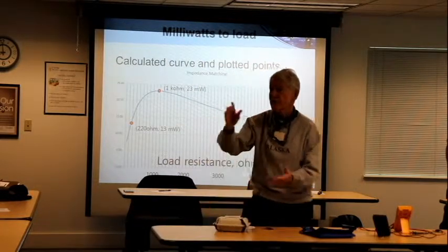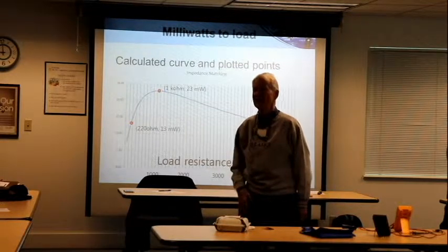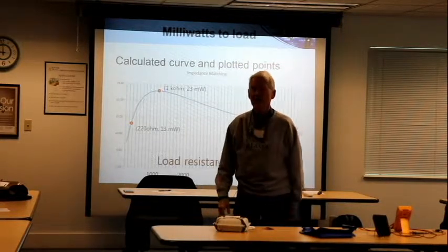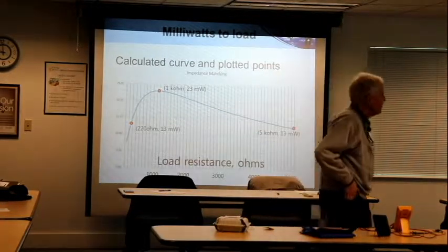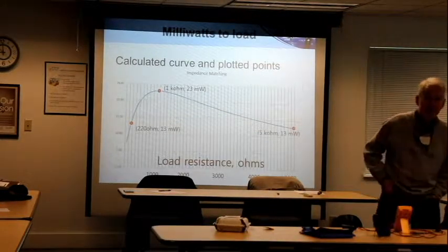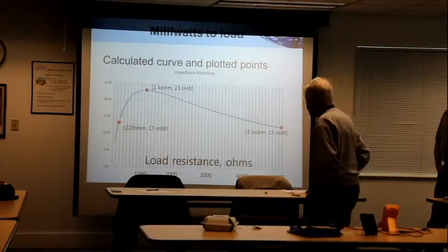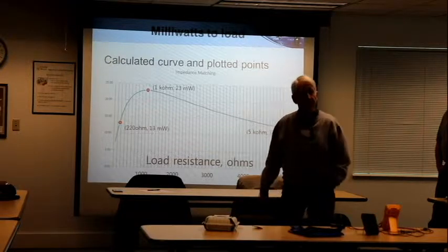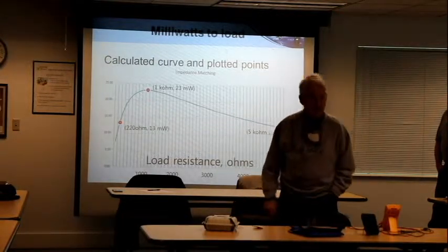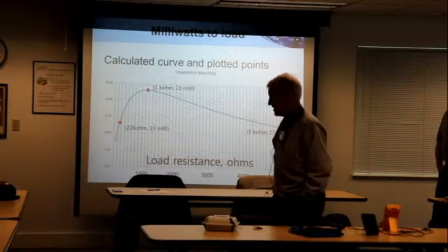And it happens that those 3 dots are on the nice line, which, yes, it's a cooked up presentation, but that's what we did today, was to show the efficiency. And it happens if you're doing antenna matching to a transmitter that you would also have at that top point the minimum SWR close to 1 to 1 for other reasons that could be clarified.